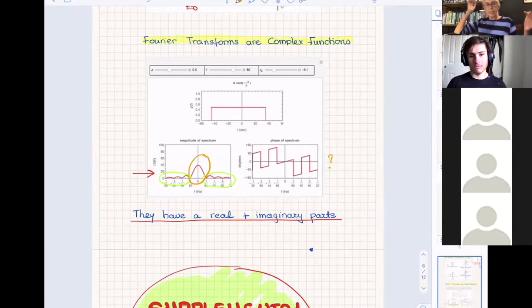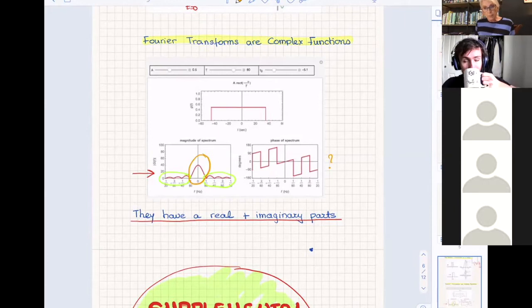If I know how much it is in two frequencies, I know how much it's going to be in the rest of the frequencies. I can extract it. I don't want to add more phase into whatever comes through my filter. So in a receiver, you need to keep in mind the following. Whatever I do to my incoming signal, I do not want to lose its information. Because if I add garbage into the signal, then I lose the information. So in everything we do, we want to be accurate and know exactly what we do to the amplitude of the signal, how we amplify it.